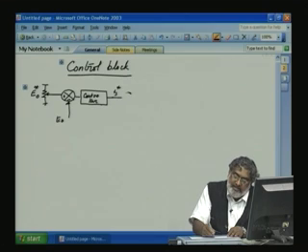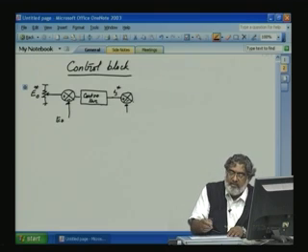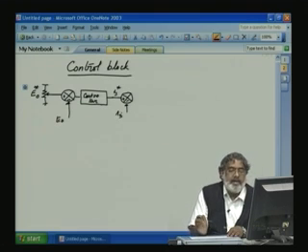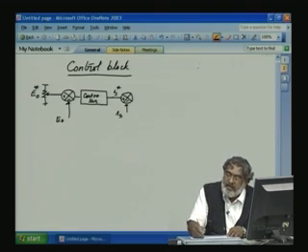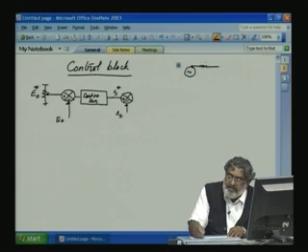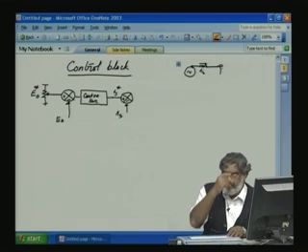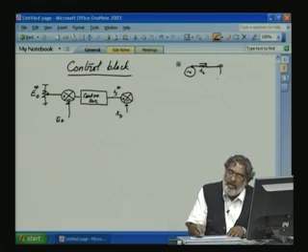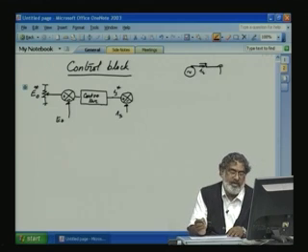This IS again we have to sense from our mains. I will just draw it here, this is our input, that is the current IS. We have to sense it using a Hall effect sensor, a LEM current sensor, and we have to properly scale it and give it here.